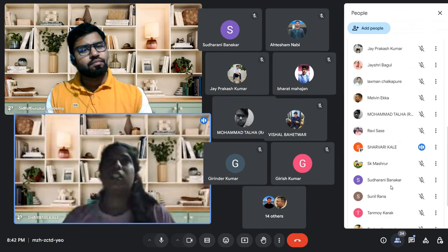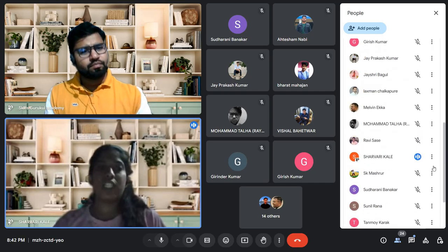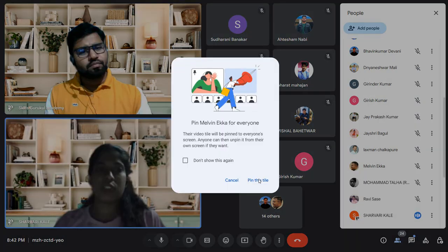If the ratio of Ly by Lx is less than 2, then the slab is two-way, and if the ratio of Ly by Lx is greater than 2, then the slab is one-way.